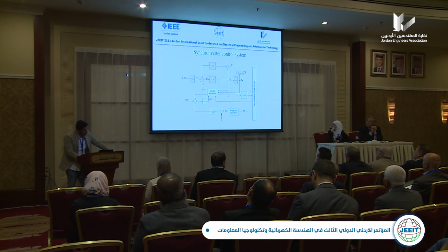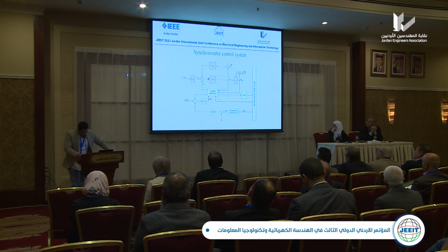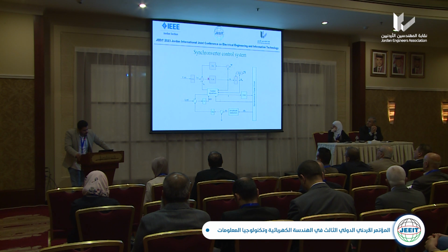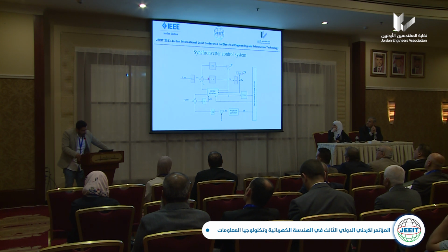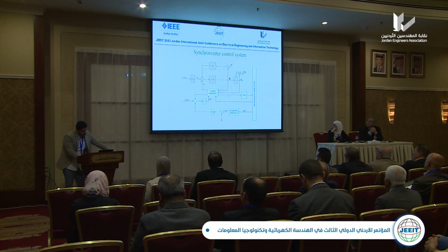The result of this summation point enters an integrator, 1 over S, and is multiplied by the virtual moment of inertia, because the inverter is static and we must behave like a real synchronous generator. The result is omega, the virtual angular frequency, which also enters an integrator, 1 over S, to give us theta.